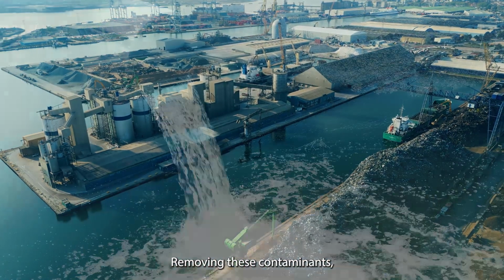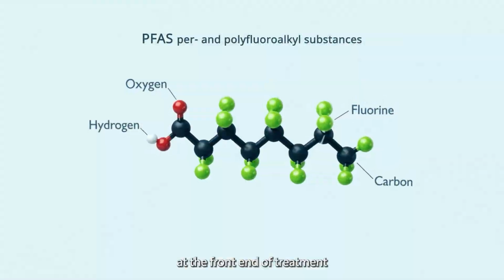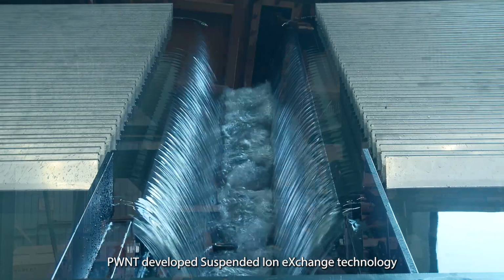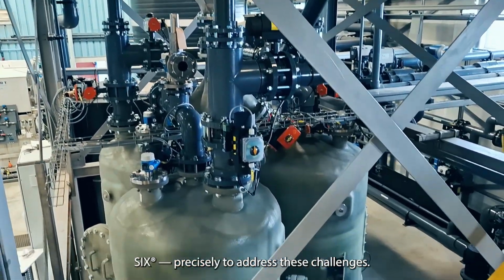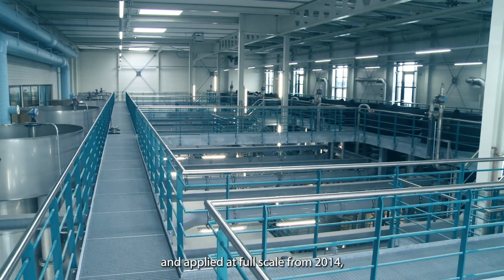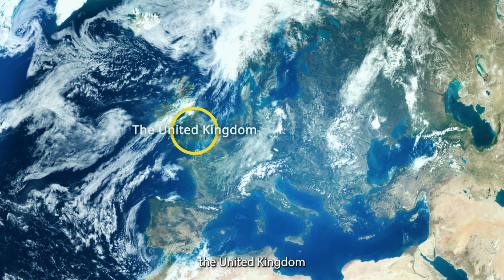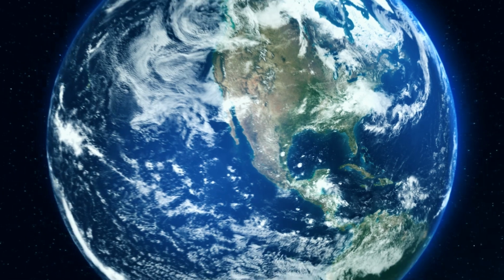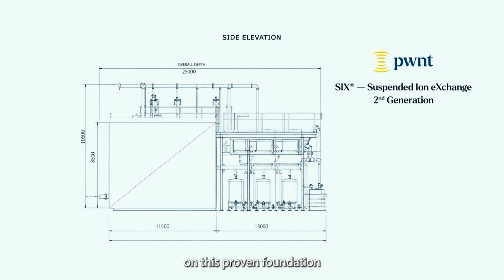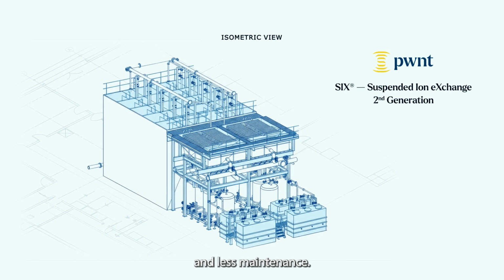Removing these contaminants, particularly persistent and harmful substances such as PFAS, at the front end of treatment is more critical than ever. PWNT developed suspended ion exchange technology, 6, precisely to address these challenges. Validated in 2011 and applied at full scale from 2014, 6 is trusted across the Netherlands, the United Kingdom, and the United States, with pilots in progress worldwide. Our second generation builds on this proven foundation, re-engineered for lower cost, smaller footprint, simpler operation, and less maintenance.